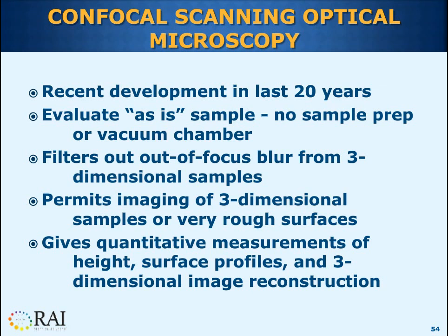The other types of microscopes which I discussed so far today usually only detect features on a flat portion of a sample. The non-flat portions of the sample will not be in focus. Other advantages of confocal microscopy are that no sample preparation is needed, and you can get quantitative measurements and visualization of the surface roughness by just putting the sample underneath the microscope lens.